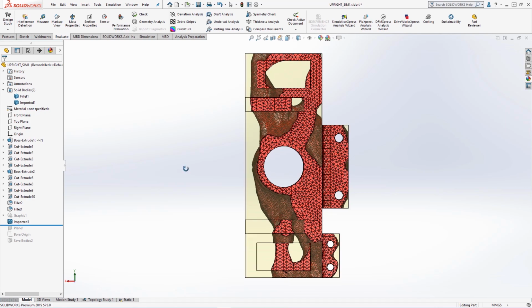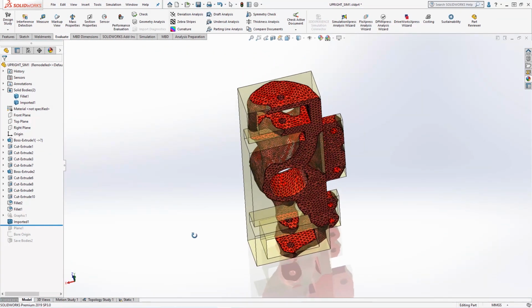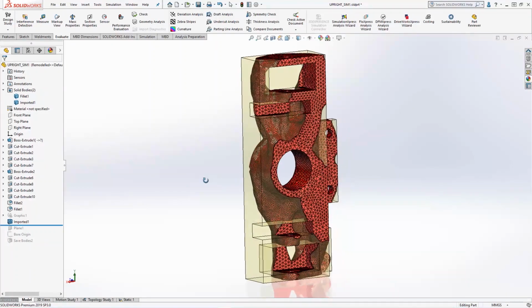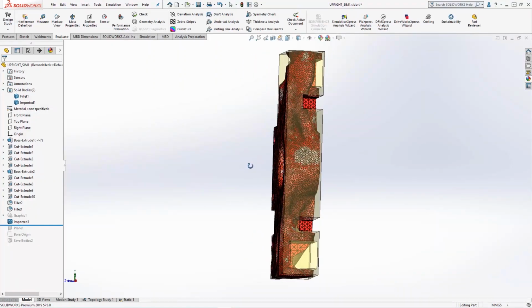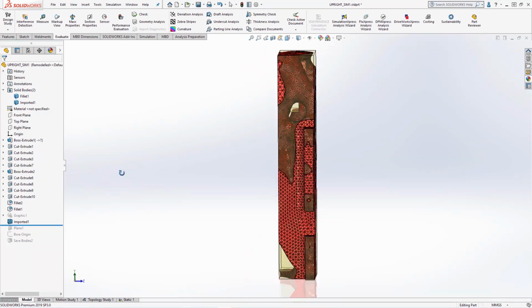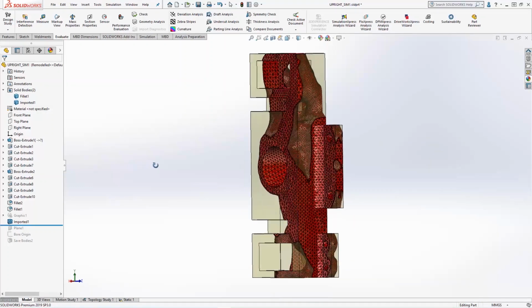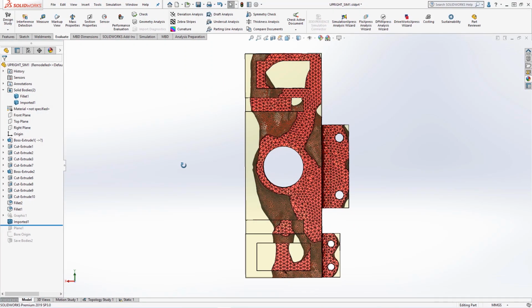A general X shape is formed around the bearing mount, and a tapered loft profile can also be seen when viewed from the side, with some clear areas that can be machined out completely. These insights can be used to redesign the component into a more easily manufactured traditional shape or manipulated further for 3D printing using advanced SolidWorks tools.